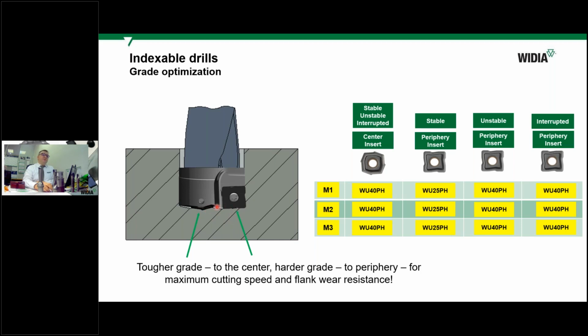That's why it's better to use different grades, different carbides, on different diameters. With indexable drills it's easier to do this. With solid carbide, it's almost impossible. There are technologies of sintering different substrates at different levels of solid carbide, but generally they are specific tools, and they are even more expensive than usual solid carbide drills.